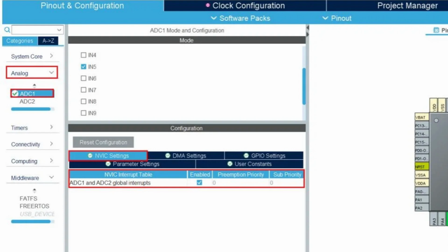What happens when the ADC finishes? When the ADC completes its conversion, it automatically sets an internal flag and generates an interrupt signal. The microcontroller's interrupt controller hardware sees this signal and automatically redirects the CPU to execute a specific function, an interrupt service routine, ISR. In the context of the HAL library often used with STM32, this ISR then typically calls a predefined callback function, like HAL_ADC_ConvCpltCallback.